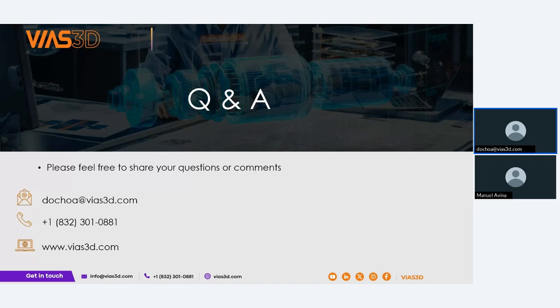That's one thing. The other thing is check your material properties. I briefly mentioned that, I think, but if you're doing radiation, for example, you should consider emissivity. So make sure you have emissivity properties assigned to that material. Okay. If you're doing convection, make sure that you have dynamic viscosity, for example, assigned to that material.